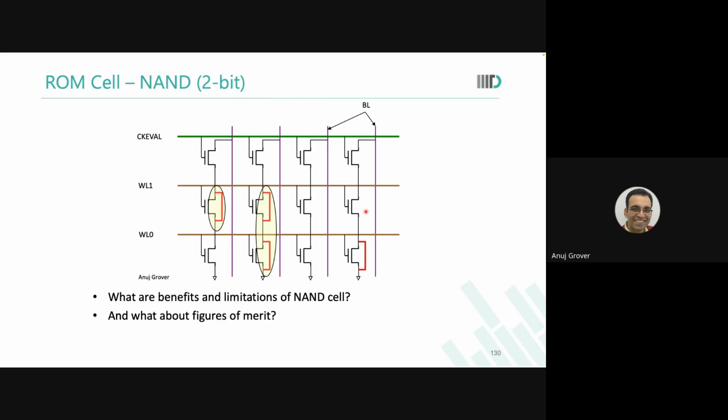And what are the advantages of a NAND cell? They are denser. Disadvantage, they have lesser current. It's a NAND stack. They have lesser current because, see, even when I turn on, suppose I unselected word line I have kept high. So all the transistors there will conduct current now. Are you with me? Now, even if I have kept the word line high, do you realize that every transistor has some on resistance? Even if it is 10 ohms, even if it is 20 ohms or 100 ohms.